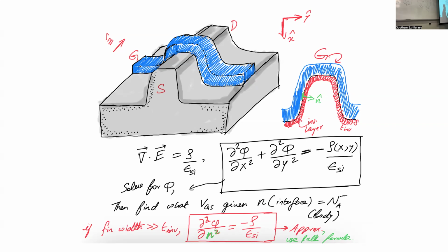But where's the heavily doped region? No, the silicon germanium is the heavily doped region. See, it's in situ doped. In situ doped means that you grow it and it's doped. So when you grow epitaxially, you add arsenic gas into it, for example, right? And then as it grows, it becomes doped. So there's no reason to do a heavy doping. In this case, you can in situ dope it.